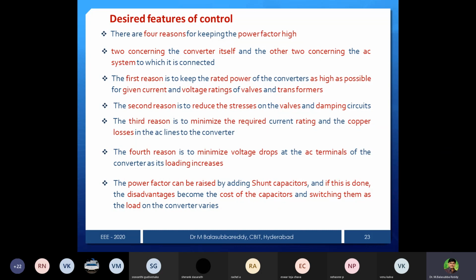So what that will do, the motor in a transmission line absorbs the reactive power. If you are observing the reactive power absorption, automatically the voltage will drop down. So if you are operating many such loads in a transmission line, the voltage is going to be dropped continuously, and then the end user won't get a normal voltage or a rated voltage. Then what people have to do is compensate that.